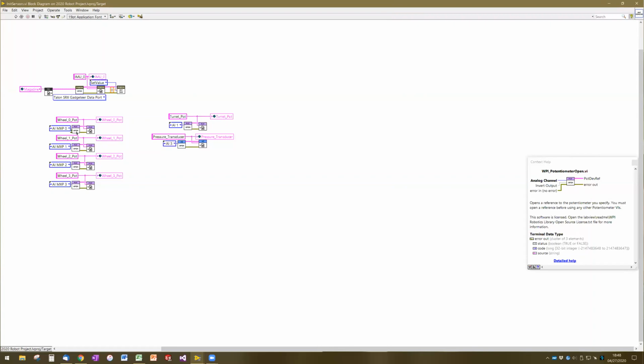If we treat it as a potentiometer, FIRST has already written the code to check that value and rescale it from 0 to 1, so we don't have to explicitly find out that 4.8 maximum value. So the output of any potentiometer read block will be from 0 to 1, with 0 being one position on the azimuth encoder and 1 being a full 360 degrees back to that original position of 0.